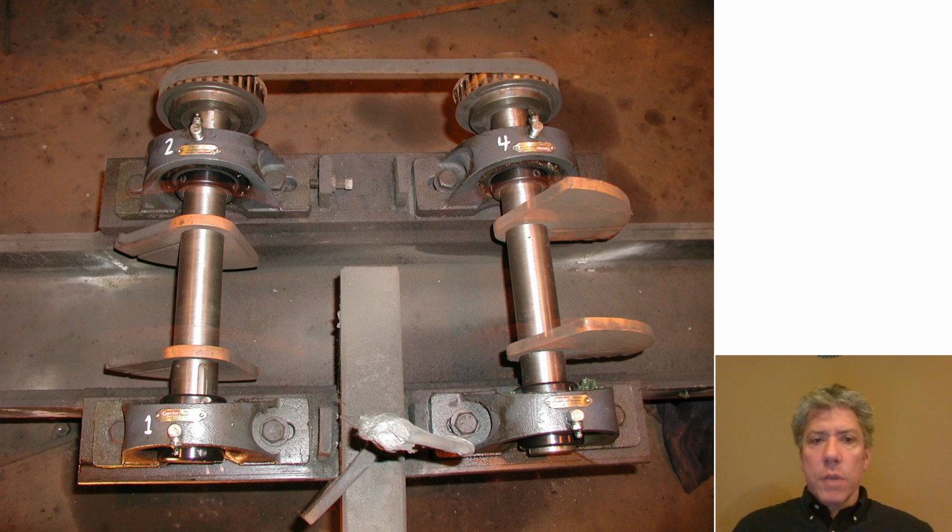Here's another closer up view of some pillow block bearings, and one thing you might notice is that the frame these are riding on has been welded, so it's not particularly precise, but the tensioning of the belt is done by what's called a jack screw. That little screw in the upper left section controls bearing 2's position, and can be turned to tension the belt and move the entire pillow block along, and then the screws can be tightened down to clamp bearing number 2 in position. It looks like there are 4 separate flanges that have been welded in place and threaded so that a jack screw can be inserted and the position of all 4 bearings can be adjusted.